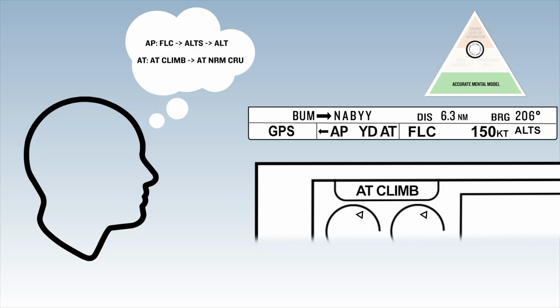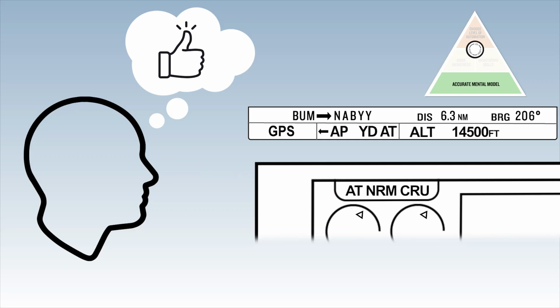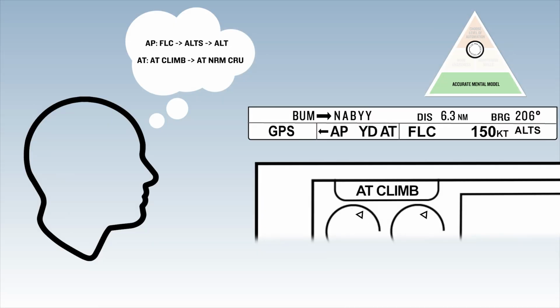During the flight, you should pay attention to how the autothrottle responds to changes in the vertical AFCS mode and compare the actual state of the airplane to what you expect. If the autothrottle mode transitions and moves the power levers as you expect, then you have an accurate mental model of the automation. If the autothrottle does not respond as you expect, your mental model may be incomplete. It may be responding exactly as designed, but you don't fully understand the logic behind the response.